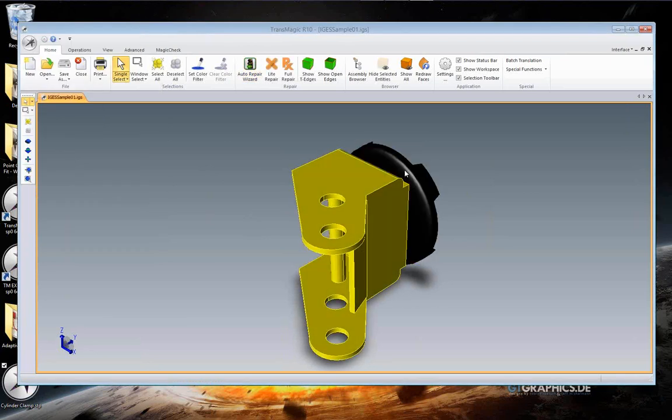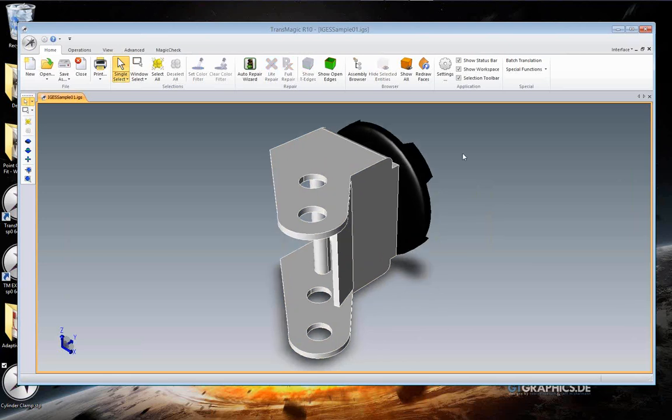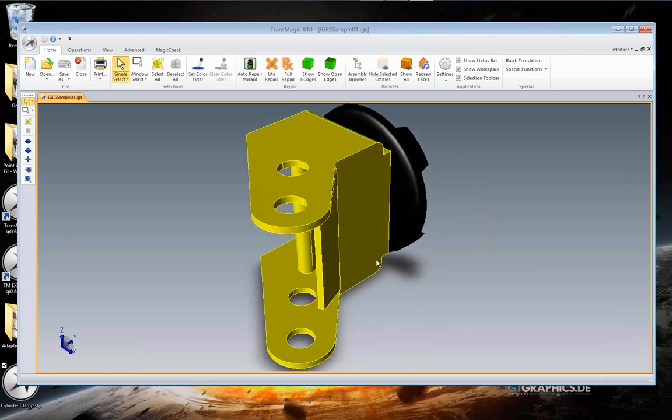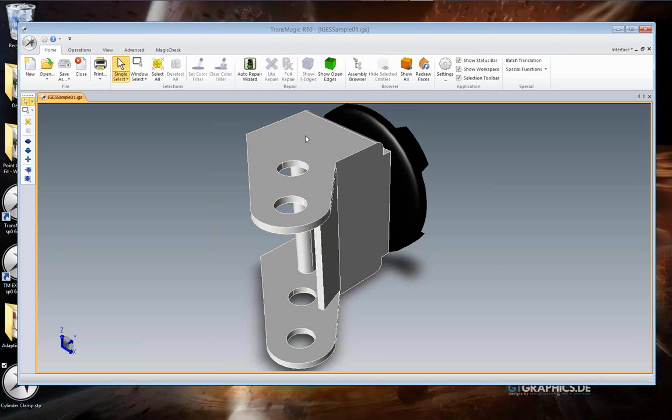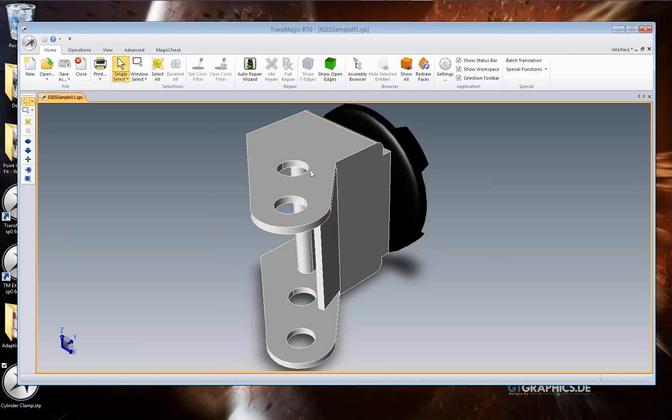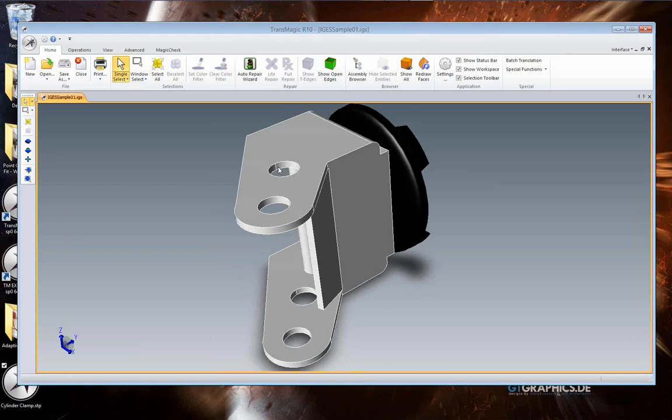So now you're ready to save that out. So instead of surfaces, we now have volume. The other thing here is it's an IGES model, so all we've done is stitch this together. We have not done anything to change the quote-unquote design intent. However, because it's an IGES, all of these surfaces are, in most cases, again, not all but most, spline surfaces. So even though this looks like a plane, this looks like a torus, a cylinder, they're all spline surfaces, and they have this split periodic.